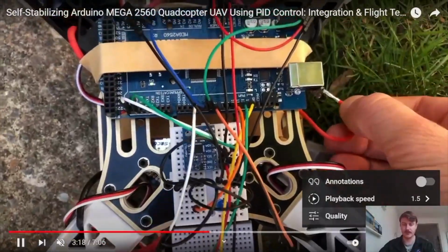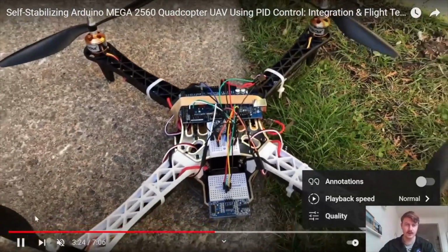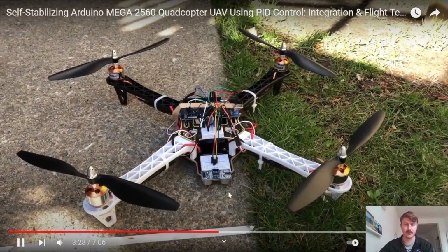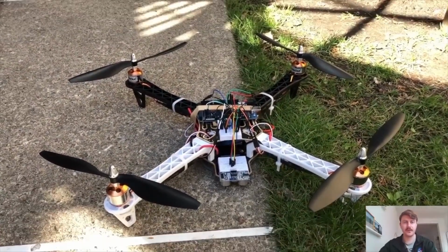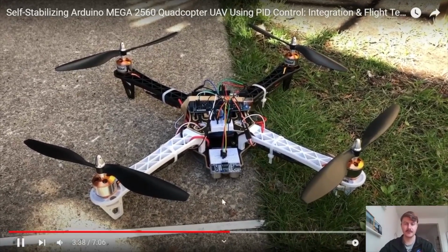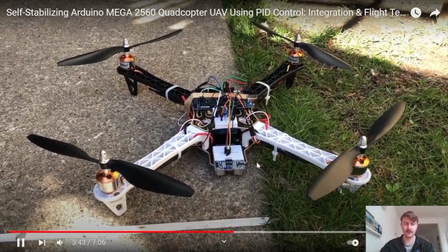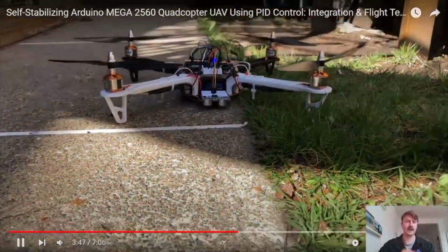So this is the part that's a little bit more relevant in the control systems. The battery's connected. I'm going to unmute this so we can hear it start up. There are the beeps for its startup phase. Its blinking LED means that it's calibrating the ESCs, which control the speed, the RPMs of the propellers, and therefore the thrust and lift and balance of each axis.